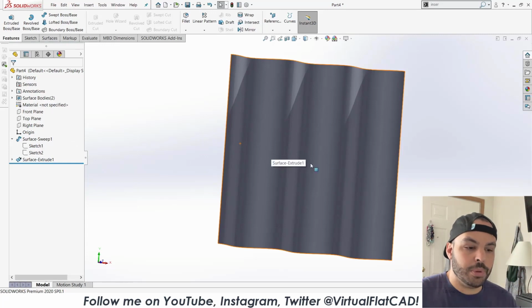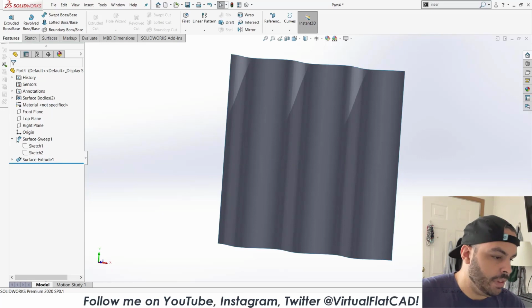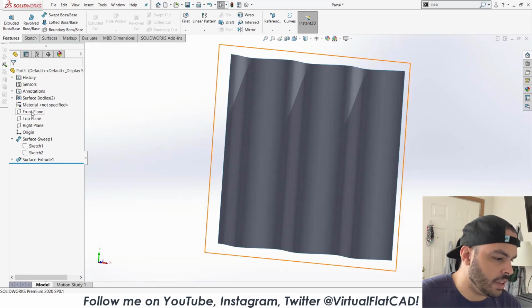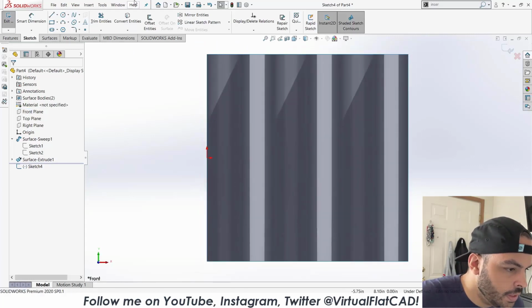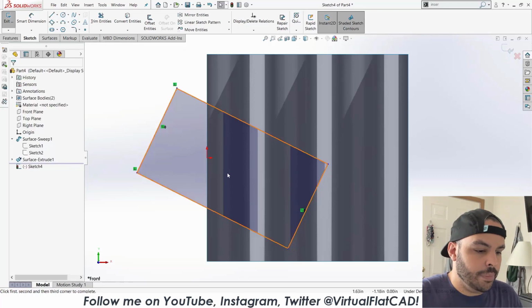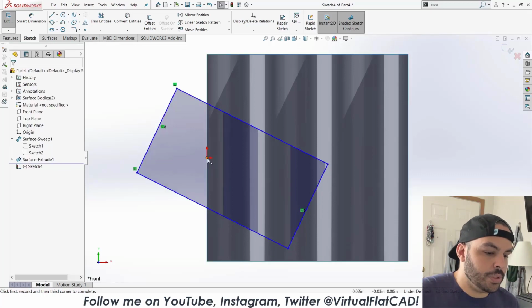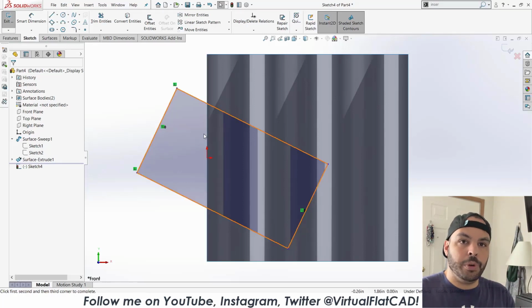So now I need to cut out the shape of my flag. I'm going to create a kind of cookie cutter sketch. We're going to start on our front plane here, and go for a 3-point corner rectangle, and I'll just draw it out here. I want to make sure that I snap to the origin rather than, for example, to the edge of the surface. It's just better practice for not creating dependencies on other bodies.